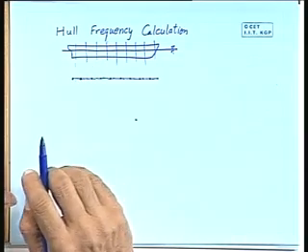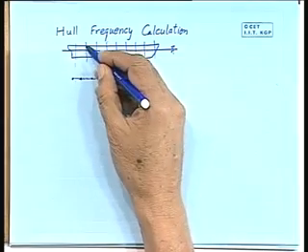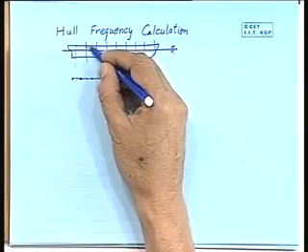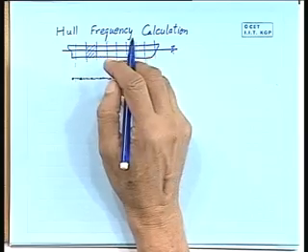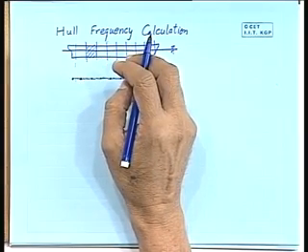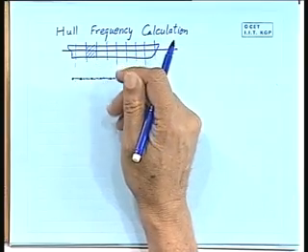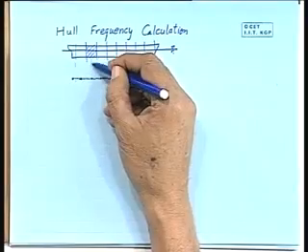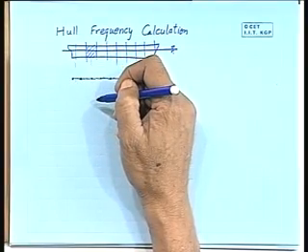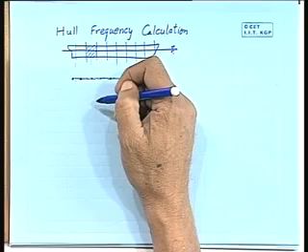What is this mass? This mass is the mass of this part completely: hull and cargo, any other mass being carried within this space, and then we also talked about added mass. So, we add the added mass of that. And how is the added mass calculated? We know that this is the cross section, so the underwater cross section is known, and we try to find out what the CV of that is, and then we add it. So, here that calculation of added mass will come into the picture.